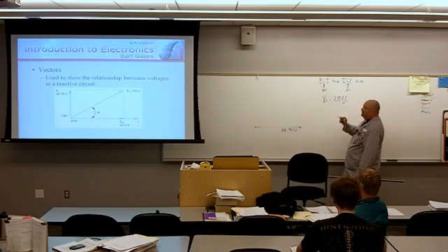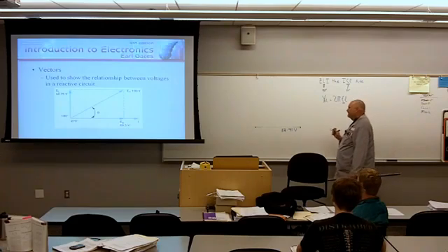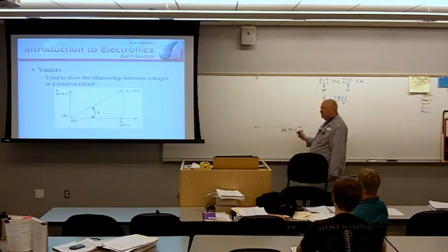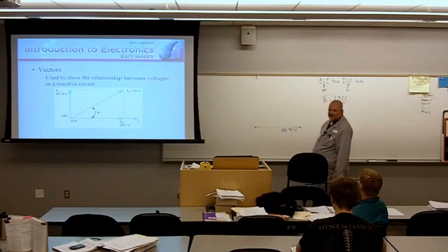What does voltage do in an inductive circuit? It leads current, okay? So what we have to do is show a 90-degree phase difference between the voltage of the resistor and the voltage of the inductor, because there is a 90 degrees phase difference between the two. Remember that 90 degrees difference?